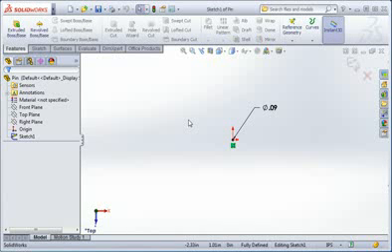Now that you've been introduced to sketches, you're going to extrude the circle to create the pin. Before we do that, we're going to look at the current status of the sketch. If you look in the Feature Manager, you can see that the sketch is now above the rollback bar. And since the origin symbol is still visible, we're still in sketch mode.